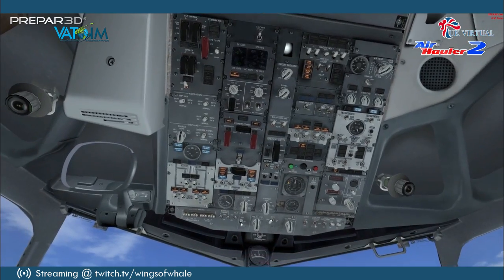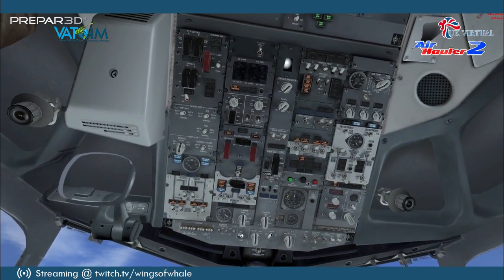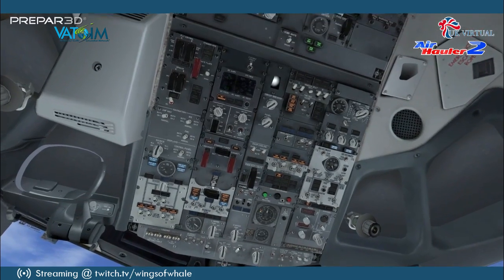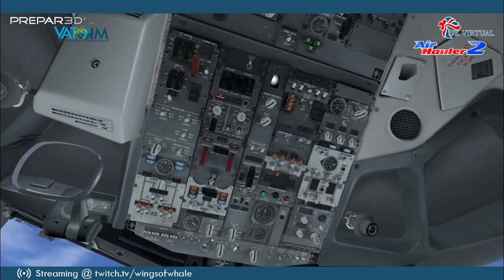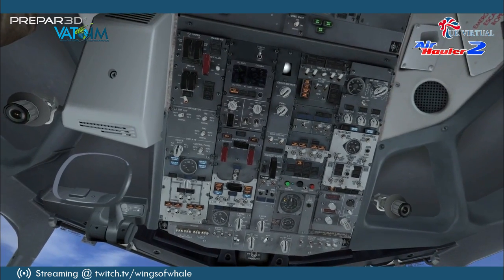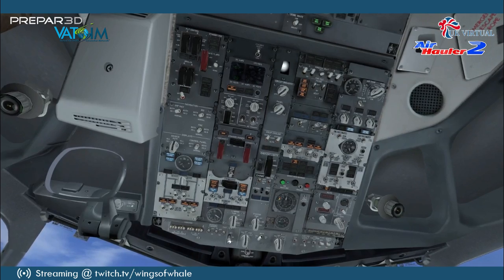So we're not using ground power. You can see it's off there. So we're going to start the APU up now. So if you do use ground power, remember before you do your pushback, you would have to start your APU before you turn the ground power off, so that you've got juice in the plane when you do your pushback for engine startup. So I'm going to go ahead and start the APU.